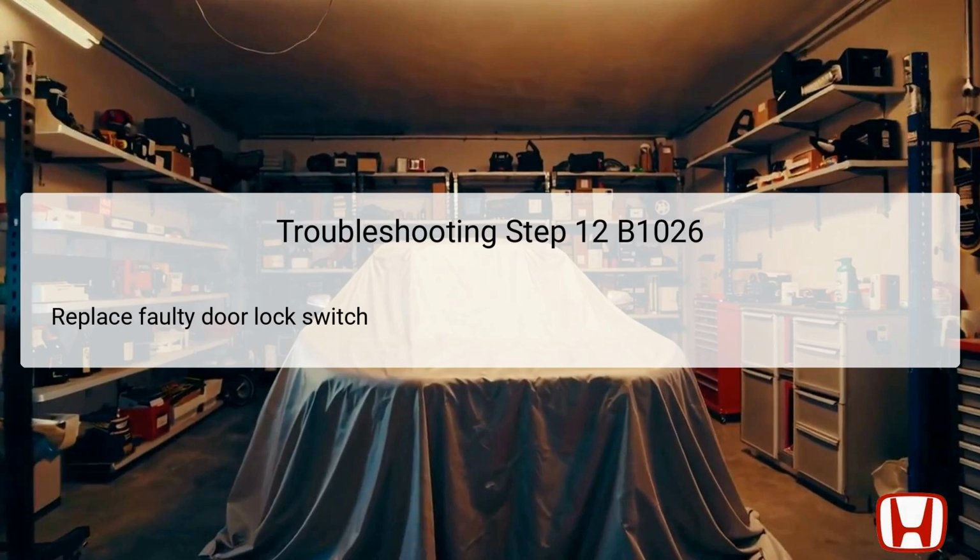In the 12th step, technicians will proceed with replacing the faulty door lock switch if both indicators were found off during the last continuity test. The door lock switch plays a vital role in the operation of the locking system, and replacing a defective one should restore normal functionality. It is critical to ensure that only OEM, original equipment manufacturer, parts are utilized for replacement to guarantee compatibility and reliability.